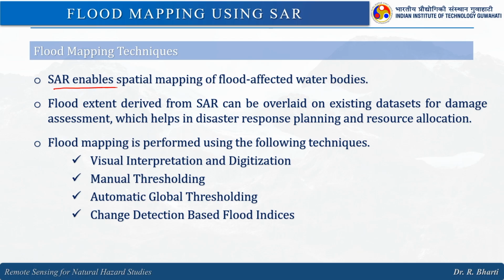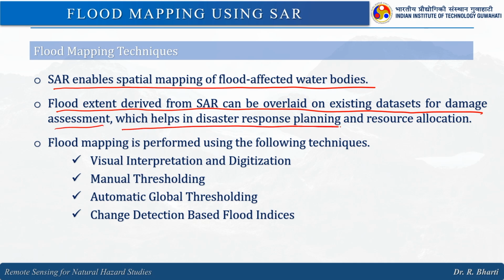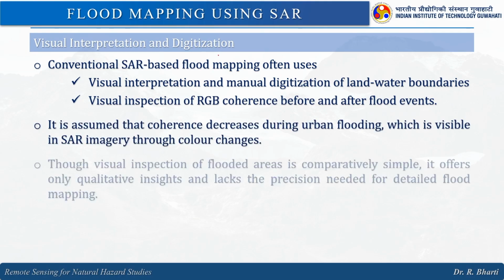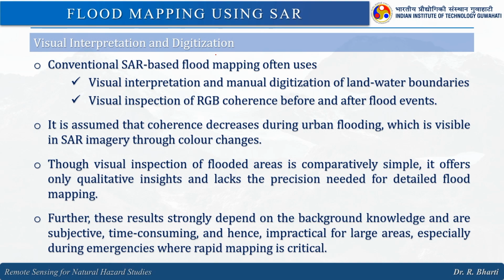SAR enables spatial mapping of flood affected water bodies. Flood extent derived from SAR can be overlaid on existing data sets for damage assessment, which helps in disaster response planning and resource allocation. Then flood mapping is performed using the following techniques. The first one is visual interpretation and digitization. Then we have manual thresholding, then automatic global thresholding, and change detection based flood indices, right.